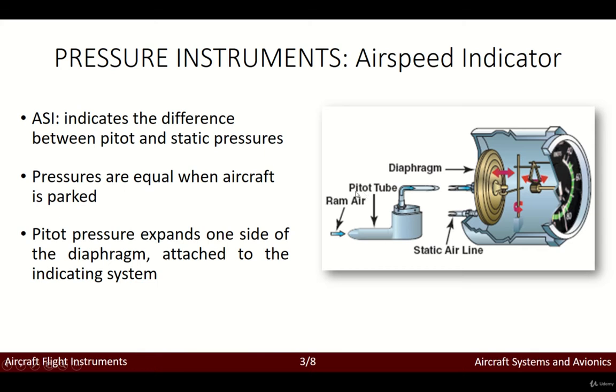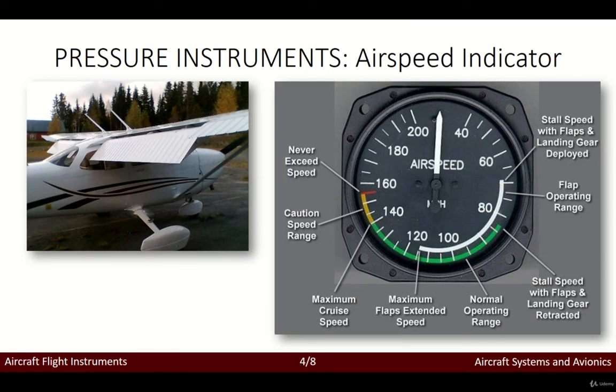So quickly, because we have a velocity, this velocity is converted to pitot pressure or total pressure, dynamic pressure. This dynamic pressure moves the diaphragm and the diaphragm moves the indicator, right? Okay, right, so what else? In terms of the airspeed indicator, we also need to check a bit how it operates, right? So we basically have a few elements which are essential.